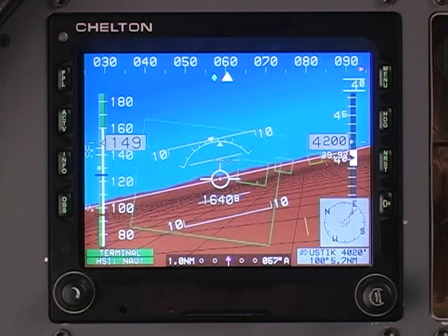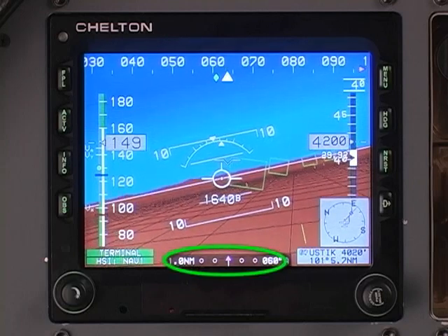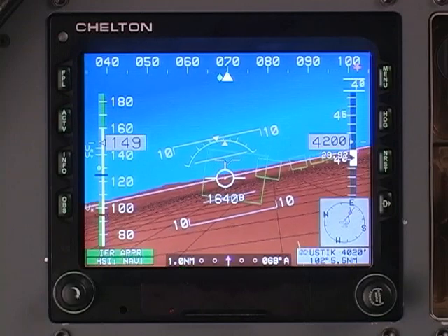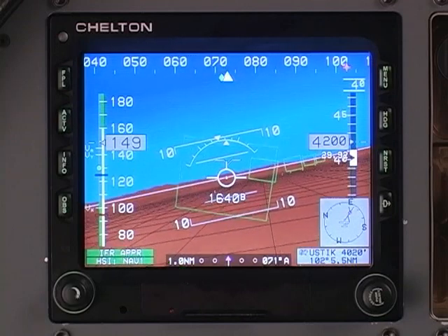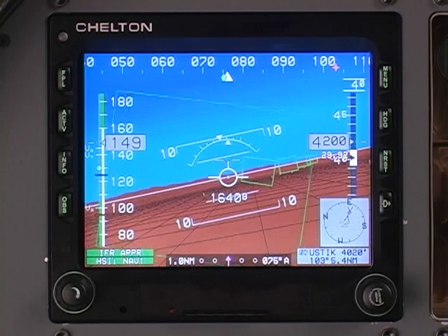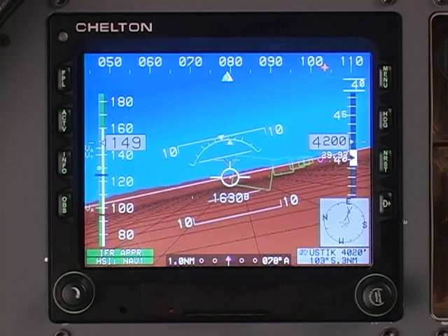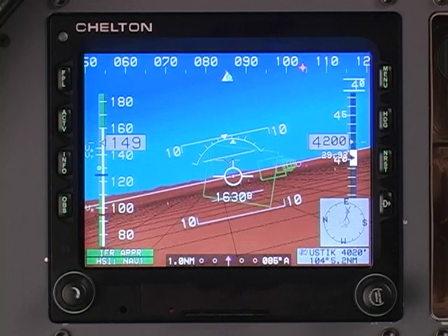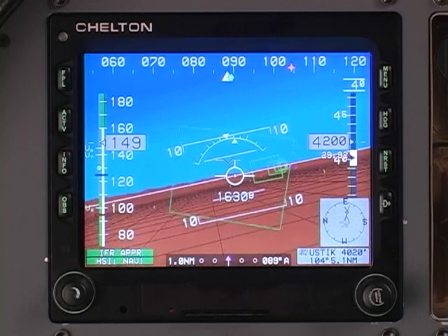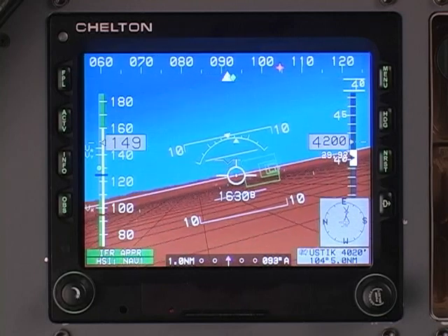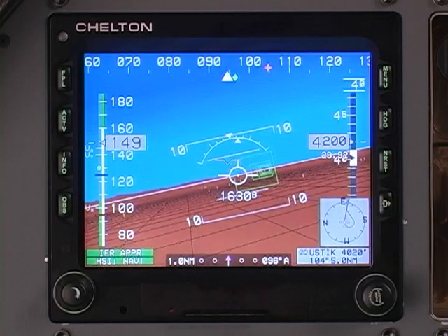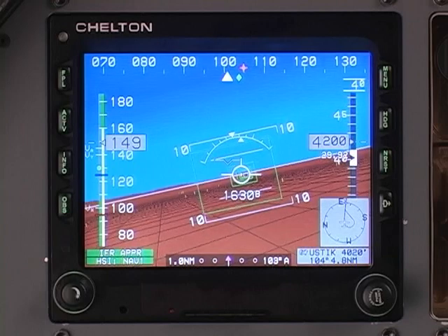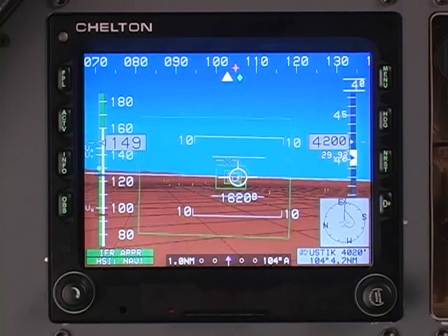The CDI at the bottom of the PFD is your primary navigation cue, but if you are anywhere near the Skyway boxes, the CDI will be nearly centered. Note that, unlike conventional CDIs, this one provides deviation indication through turns. Apply small control inputs to guide the flight path marker through the boxes. Use tiny corrections, as if on a localizer, for straight segments. The nature of the flight path marker eliminates the need to compensate for winds.